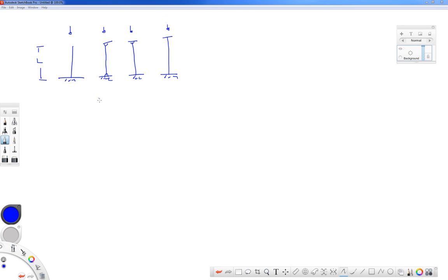All right, so let's just write our formulas down one more time. We had 4.4934 quantity squared times EI over the length of the column squared. Okay, so all of these have the length of the column L. And over here in the pinned case, we had pi squared EI over the length of the column squared. Again, we're looking at n is equal to 1. So what I'm saying is that for the same length, this holds a higher load.